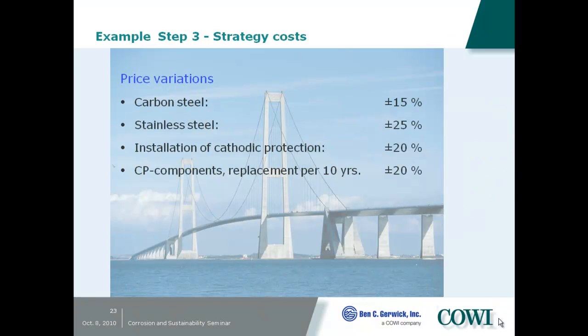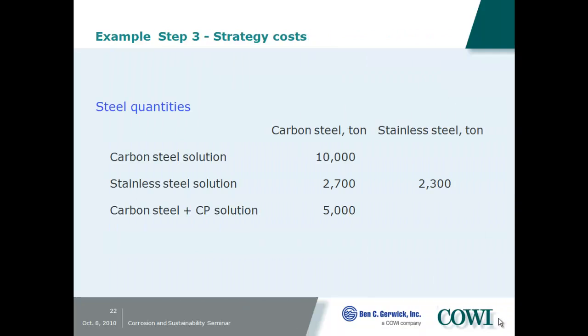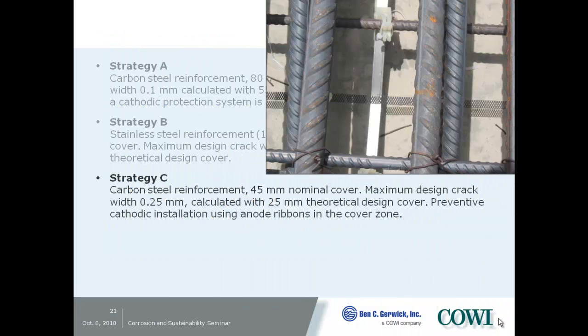Okay, I missed the last picture. Can you go back to the picture of an anode? Yeah. We'll have a presentation on cathodic protection later. You have the reinforcement bar here. And underneath, you can see there's an anode placed here. That's the ribbon. So that's a mixed metal oxide titanium coated ribbon. And then you have a current feeder. That means where current is introduced to your structure, and it will then distribute along those. We'll get back to the principles on how this works when we have the cathodic protection presentation later.